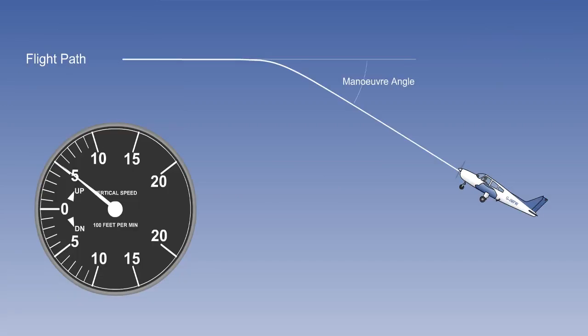The third error to consider is maneuver-induced error. Again, this error is related to the source of the static pressure. Short-term fluctuations in pressure at the static source during attitude changes, especially during changes in pitch, will cause the VSI to indicate a false reading. This error is especially noticeable during pitch changes, which occur with flaps and landing gear operation.